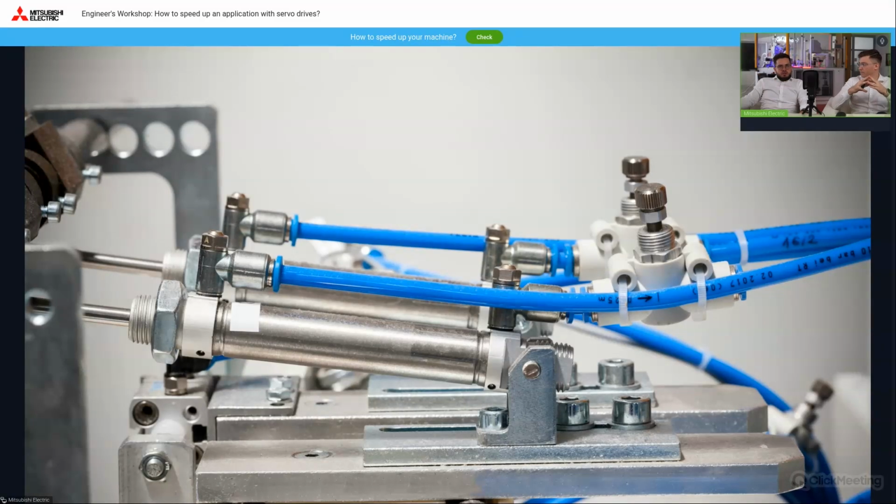Okay, in pneumatic actuators, traveling time depends on pressure and flow. Over time, due to the leaks that develop, we will have to use more medium, which is very negative for the energy efficiency, but that topic is for totally another meeting. Let's go back to accelerating the machines, because all in all, at a certain point we will reach the maximum pressure and flow, and there will be no way to accelerate the actuator. Moreover, the machine culture will be bad, the actuators will wear out quickly, and we can't take advantage of the other control benefits that the servo system gives us.